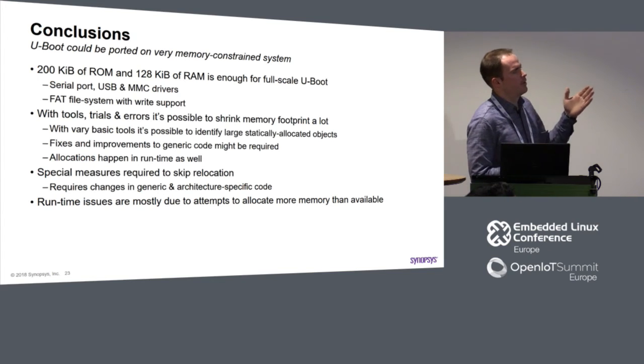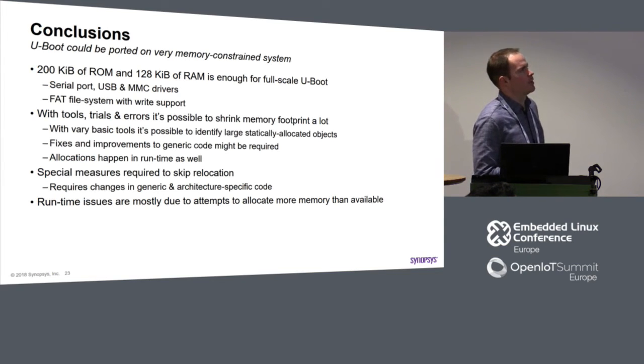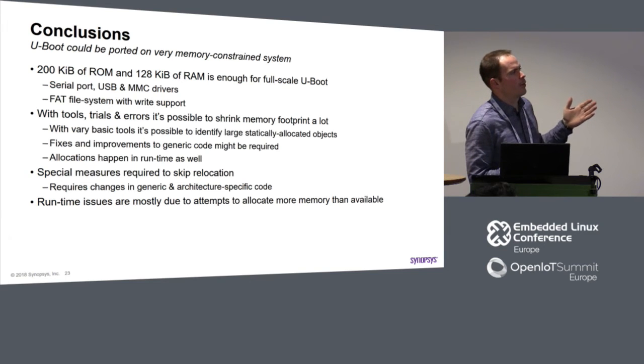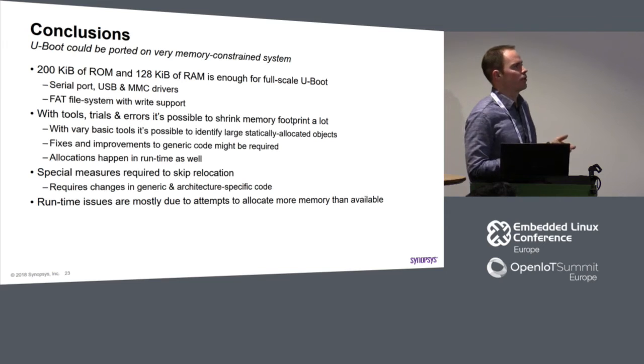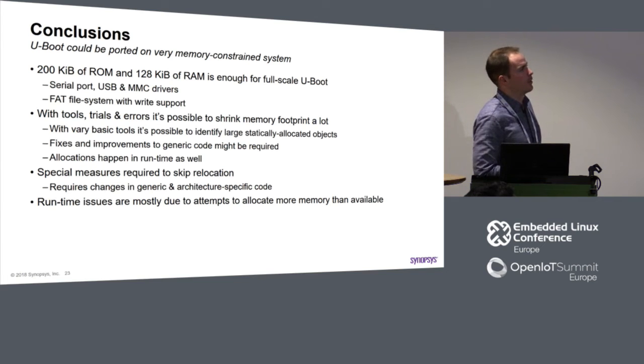For this particular case, I was able to squeeze it into 200 kilobytes of ROM and 100 kilobytes of RAM. And still I got drivers for serial ports, USB, MMC, and support of the FAT file system, not even just for reading, but for writing as well, because we expect a user to keep an environment on an SD card or USB storage.